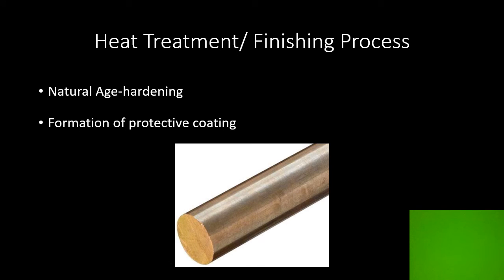One of the characteristics of brass is that it naturally age hardens at room temperature. This means that the handle will resist scratches without the application of any post-manufacturing heat treatments. The outer color of brass starts similar to gold and then darkens with age. This darker tarnish is the protective oxide coating that is formed. This oxide coating may not form in high handling areas of a brass piece, but the material has favorable corrosion resistance, even without this layer.